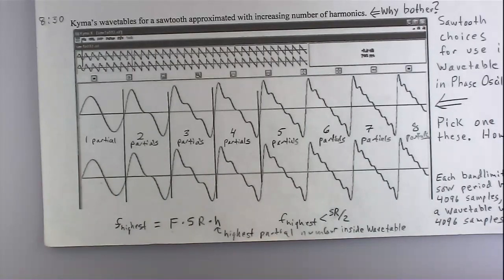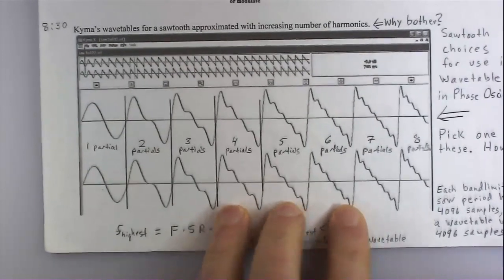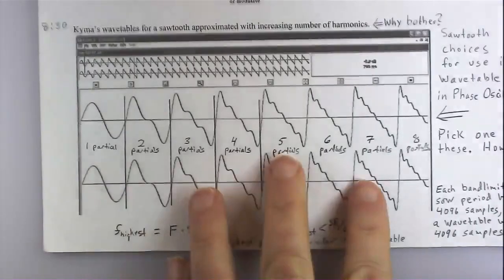Similarly, if you want to make a square wave in the digital world, you can't just have a function that goes from maximum value to minimum value and then stays at minimum value for a while and goes back to maximum value. That's a piece of garbage. That's not a digital square wave. It would be fine in analog because you don't have a half sample rate in analog. You can do that kind of thing in analog. But in digital, you have to limit it to the half sample rate. What do they call this thing? A Gibbs phenomenon? Do you use that word? No? Yes? I see some of you. Okay. But anyway, you sort of know this. You've seen this before, but it's really, really important in audio.